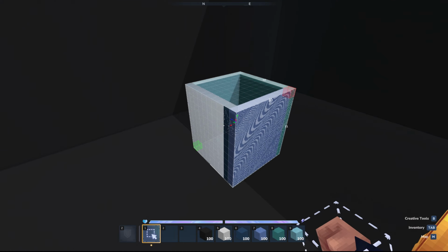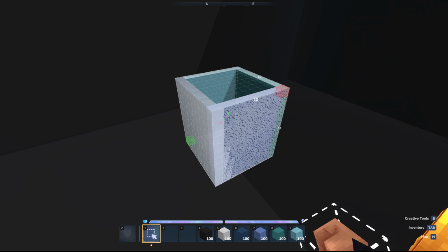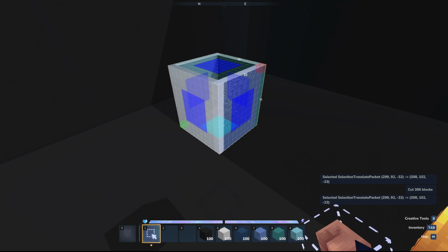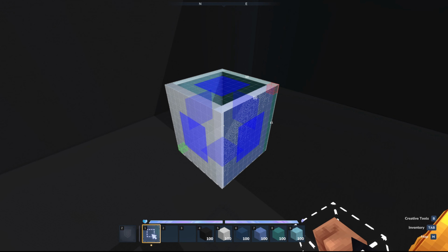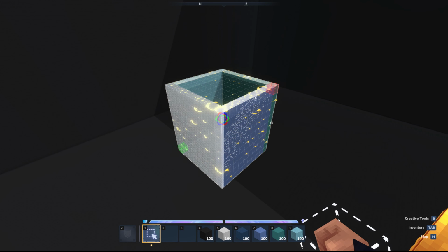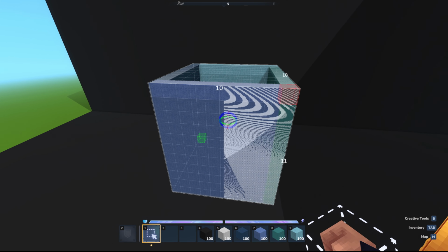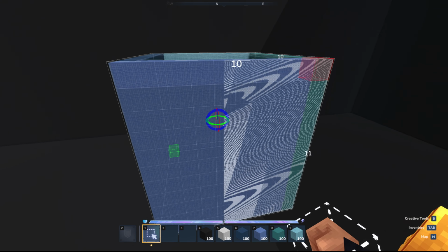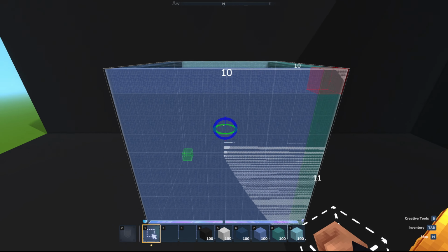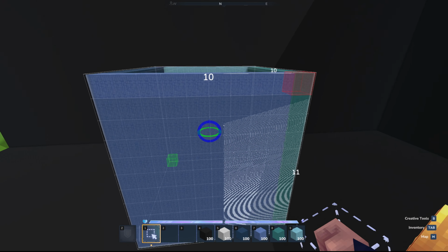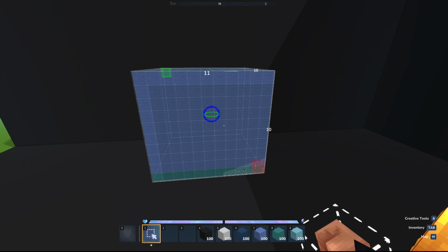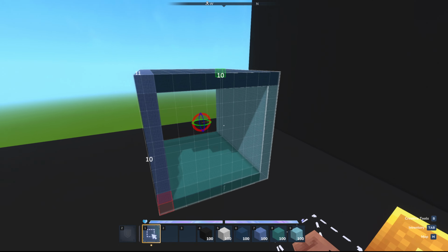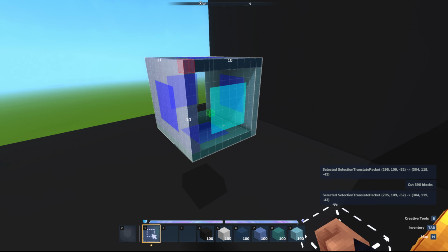So the last thing I wanted to talk about is rotation. And by the way, I need to lock in my selection by pressing right click first. Now I can do my next transformation, which is to rotate. As rotate starts with an R, you press R on your keyboard to start the rotation process. As you can see here, we have once again the three axes. If you click on one of the axes and follow the path, it's a little bit finicky, but as you can see, I rotated along the blue axis, and my rotation has been performed.